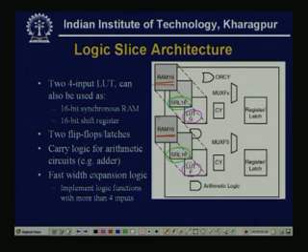So, actually if we see, this is one LUT which contains one 16-bit RAM, one 16-bit shift register and one flip flop, and this is another LUT which has the same contents, and there are 4 inputs.